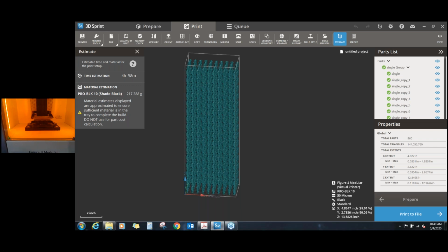Now, yes, you will have to factor in that after this print is complete, there's going to be some time that it takes to wash these parts. The wash process really entails an isopropyl alcohol dipping to remove resin. Anthony may talk about that a little bit when he shows the machine. It doesn't take too long for the cleaning with the chemicals.